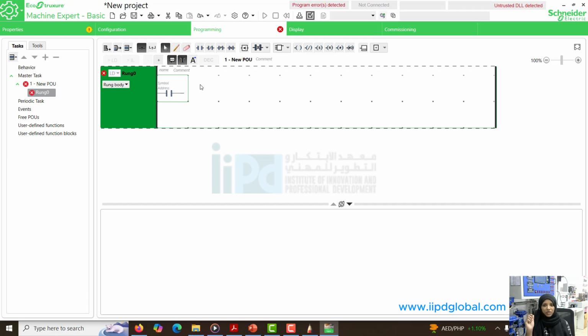So what you will do is place a sensor there. Now comes the importance of the inputs to the counters. The input to the counter will be sensors, and the sensors will be proximity sensors. It will give a pulse to the counter. Whenever a car enters the car parking area, there will be a pulse, and with this pulse the counter starts to count like 1, 2, 3, etc. Once it reaches the preset value, that is 50, you can give the command to close the door. Now this is the up counter.